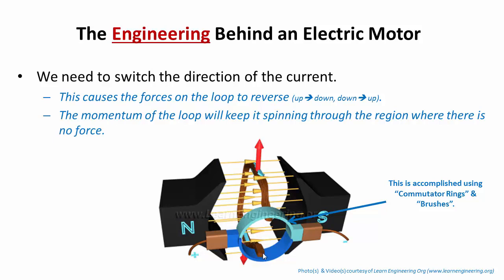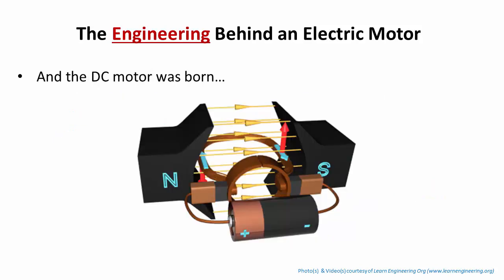or if the dark blue gets the positive side of the battery. So now in order to allow this ring to spin, the ring is actually connected to this coil of wires. They use these brushes right here that have springs in them, and this provides basically a mechanical connection. It's a spring that pushes these brushes down here, and it allows this thing to spin and make electrical contact. So that's how the DC motor was born.